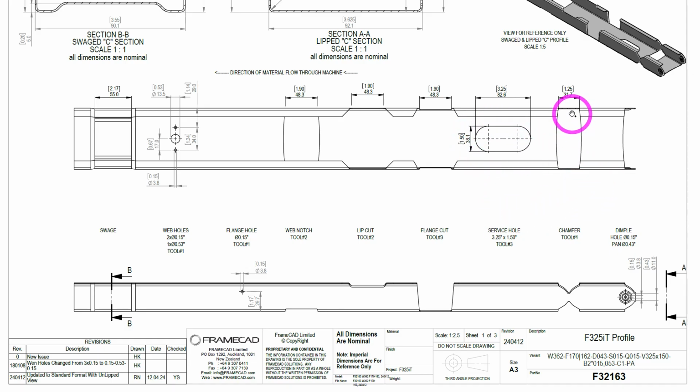We have a chamfer right here. That's what a chamfer looks like. You usually see chamfers when you have a brace component, some sort of angled piece, and it needs some extra clearance to make sure that it doesn't run into the web of another stud. We have our dimples, of course. That's what it looks like here in plan view. Can't really perceive it because it's on the sides or the flanges. So if I come to our elevation view, there's our dimples right there.